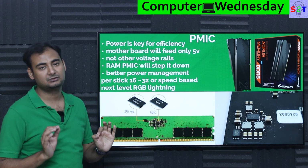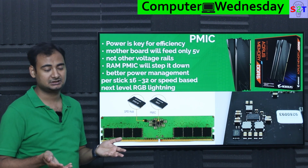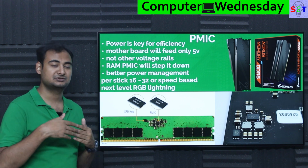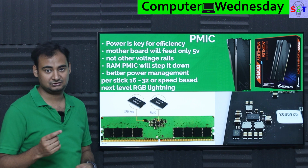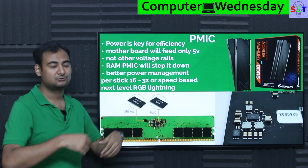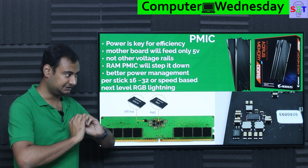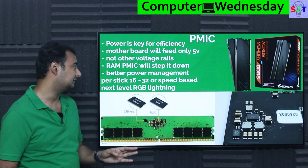The biggest change is that the motherboard will now only feed that puppy 5 volts. Now as you can understand, in the voltage and amps relationship, the higher the voltage, the lower the amps for the same amount of wattage. So even if you are consuming, let's say, the older system had to provide 1.5 volts, now this puppy will provide 5 volts. So even if it's consuming twice the power, from a motherboard trace layout point of view, it's generating less heat. So 5 volts is very good from the motherboard point of view, and they will only provide 5 volts. You take the 5 volts, of course within this amp range, and go YOLO on it. I don't have to do anything other than that.